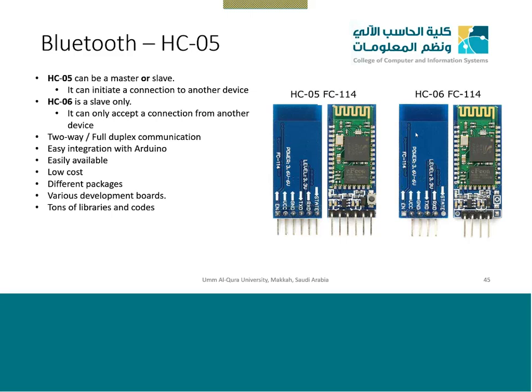If you want direct IP connectivity, use Wi-Fi. If you want indirect IP connectivity, use Bluetooth. In case of indirect connectivity, first you have to send some data to an application on a phone or on a device like a phone, and then that device will send your data forward. But for easy applications, Bluetooth is the best because it is low power and very easy to set up.